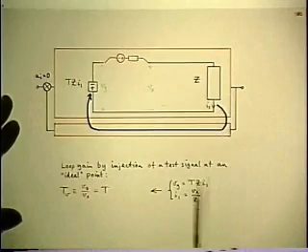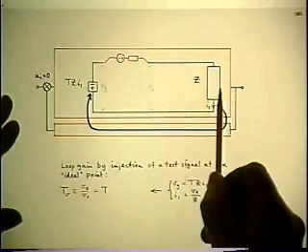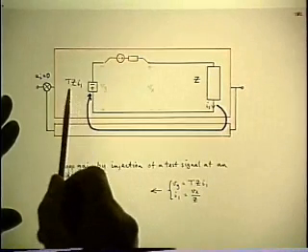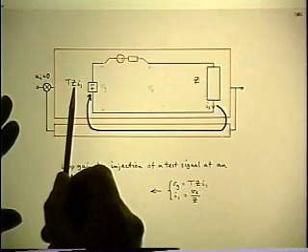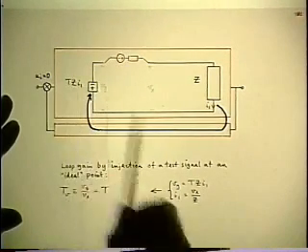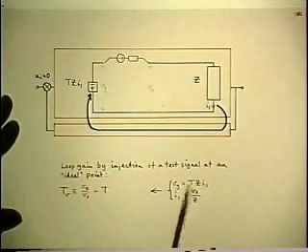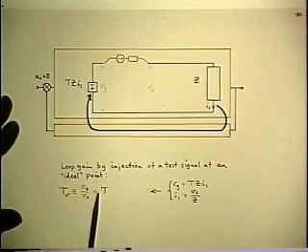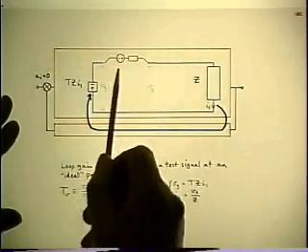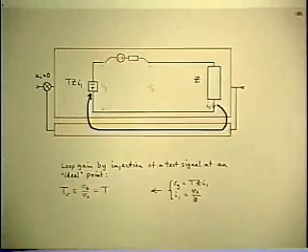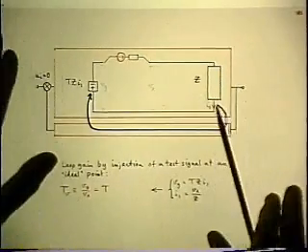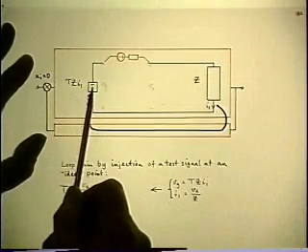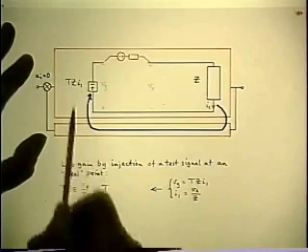So the relationship is I1 is equal to Vx over Z. I1 activates this generator, and I'm going to label the generator T times Z, I1, because that voltage is Vy. Therefore, if I divide Vy by Vx, the answer is T. And that's the correct answer because this is the ideal injection point. So all I'm saying here is I don't need all the rest of the loop. All I need is to identify the value of this generator in terms of the answer that I want to get.